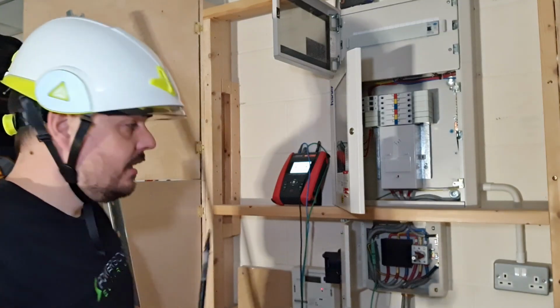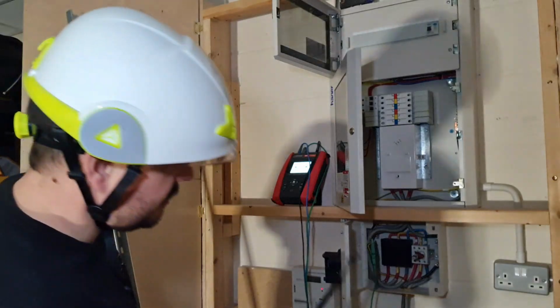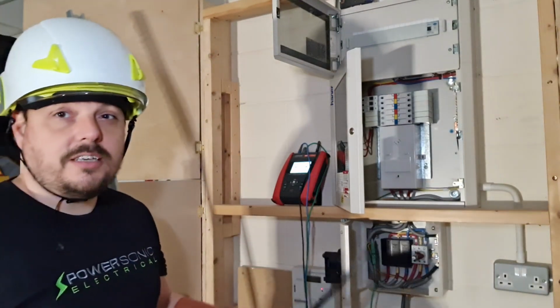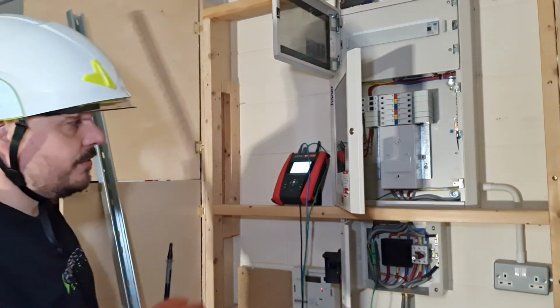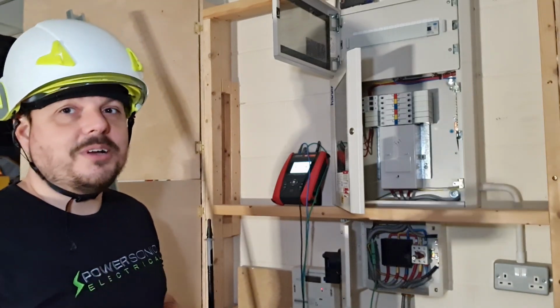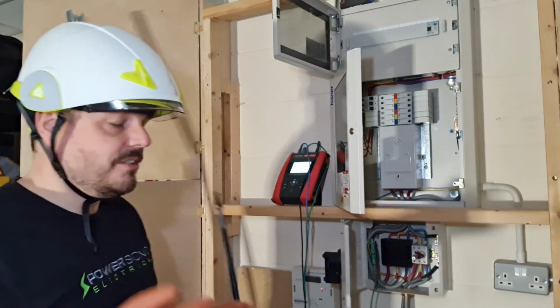I'm ready to go. We have the TIS MFT Pro, which I've already crocodile clipped onto the earth, and as I said before, these 2 enclosures aren't actually linked in the containment. There's a separation that the original installers have put in, so I could have just probed straight on, but it's as easy to just take it out and crocodile clip. So I'm doing it in the right way because the earlier video I did, when I didn't take it out, there was a few questions, it caused confusion,